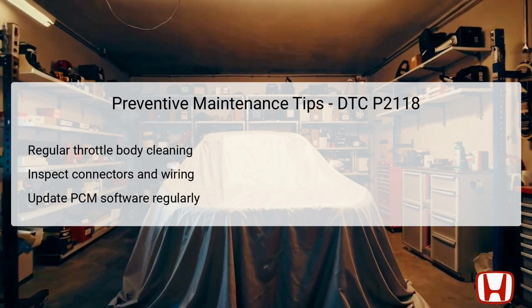To prevent the recurrence of DTC P2118, implementing a routine maintenance plan is essential. First, consider regular cleaning of the throttle body to remove any carbon buildup that could impair airflow. This simple step can significantly improve efficiency and responsiveness. Also, ensure that all connectors and related wiring are frequently inspected for wear and corrosion, as poor connections can lead to intermittent issues that trigger DTCs.